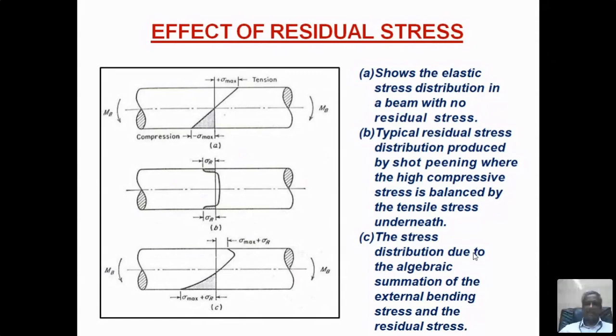Definitely, because the corrosion will introduce pits. Generally, all the corrosions, whatever the type of corrosion, they will introduce the pits first. Pits means what? Removal of material from a localized area, micron level pits, micro pits. So those pits will act as notches, stress risers. So from those pits, the crack will initiate. So fatigue crack will initiate. If there is a stress difference, stress gradients, okay, a stress rising point, definitely it will initiate from there. Okay, so corrosion is very dangerous for fatigue.